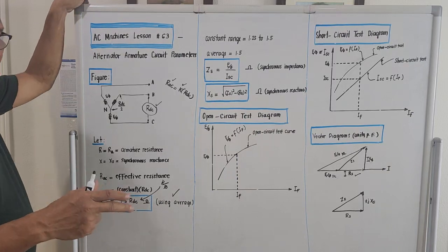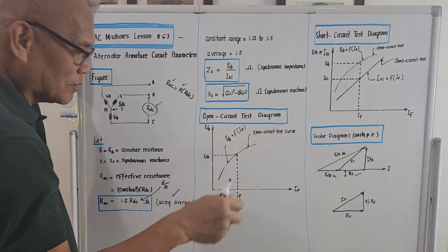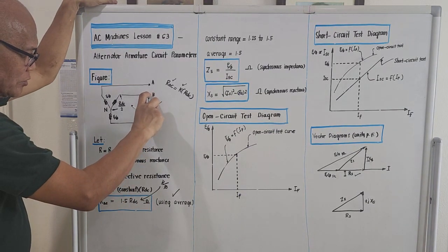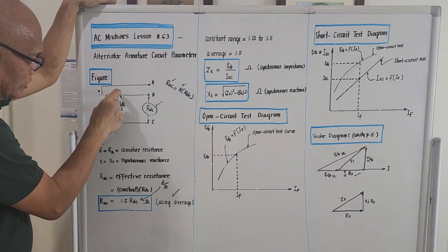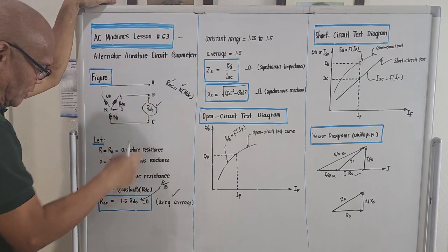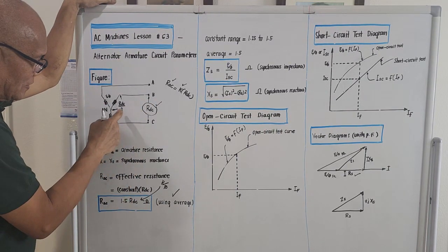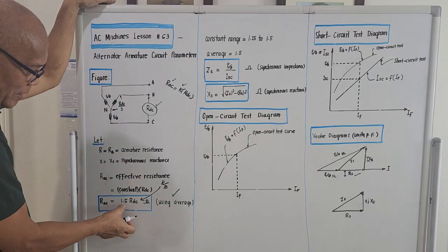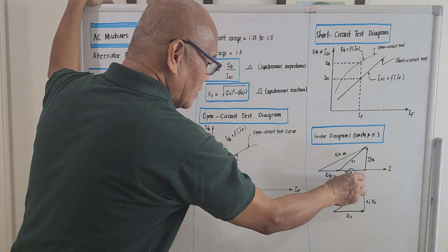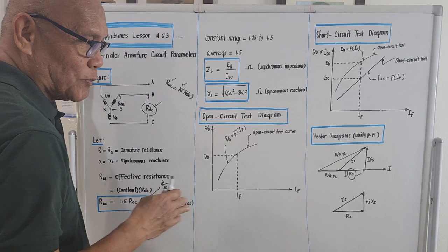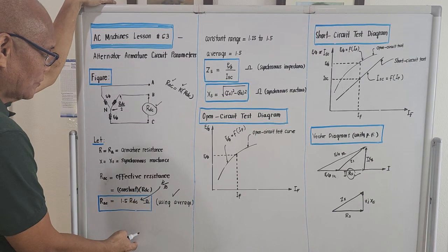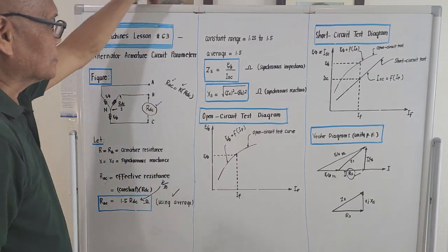So we eliminated one problem in the computation of the voltage regulation, because we now know the AC resistance. If we measure RDC over here, we divide it by 2, so we can determine the DC resistance per phase. It's balanced. So upon taking the value of RDC over 2, we multiply that by 1.5, and that will be RS, shown now here. We concentrate more on the formula side, and at least we know how we determine RAC from the reading. Okay, what's next?